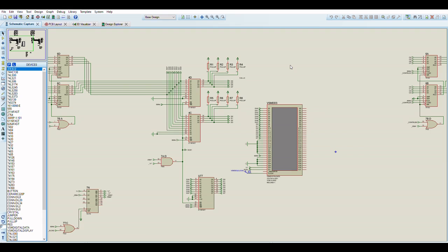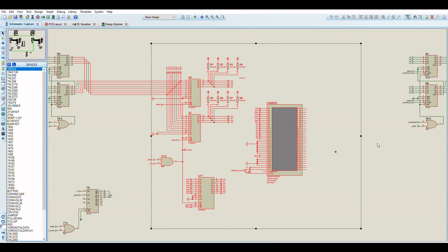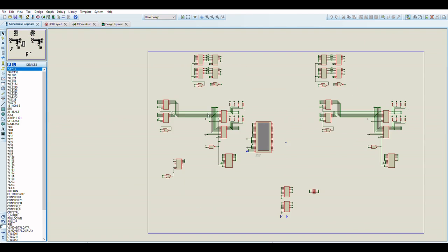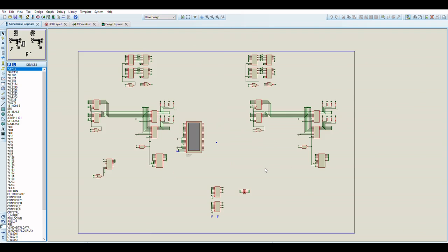Then, following up on my work on the Mode 7 screen gave me some insights into using multiple pixel calculation paths, a little bit like the horizontal scanline interleaving method being used for the sprites currently. But it meant that not just on horizontal scanlines, but also on alternate pixels, I would be doubling up on all of the circuitry, which meant doubling up again on all the circuitry here and here.